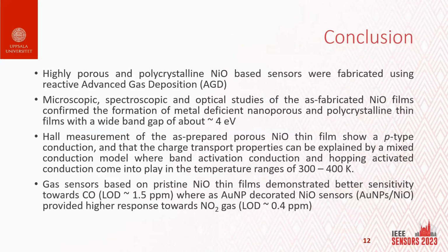Finally, my conclusion would be that we have produced highly porous nickel oxides with AGD. The microstructure study shows nanoporous polycrystalline films with a wide band gap of 4 electron volts. The Hall measurements give band activated conduction, and hopping activated conduction comes into play at lower temperatures. The gas sensor based on pristine nickel oxide produced better sensitivity towards CO, and the gold nanoparticle decorated one gives a high response towards NO2 gases.